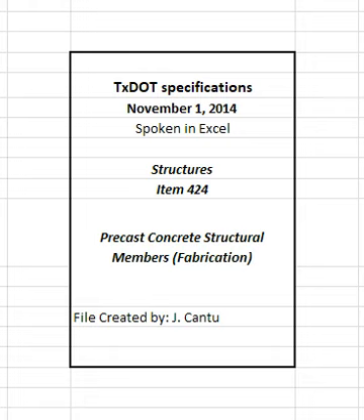Provide an unobstructed airspace of at least 6 inches between surfaces of the concrete and the curing jacket. Monitor and maintain the curing enclosure air temperature between 50 degrees Fahrenheit and 160 degrees Fahrenheit during accelerated curing for pretensioned and non-stressed concrete members.